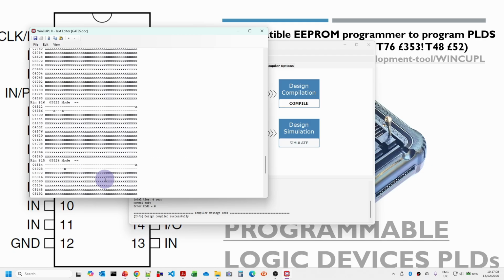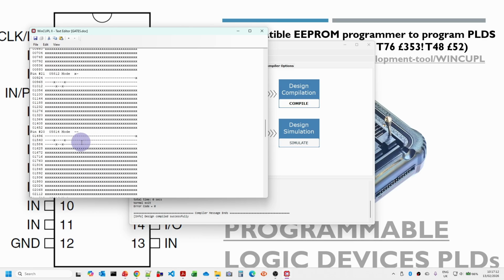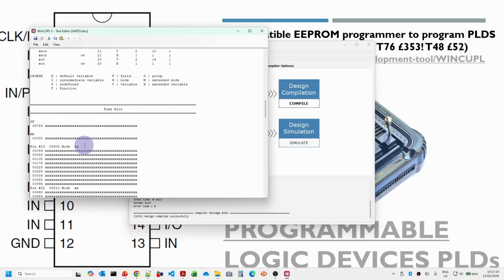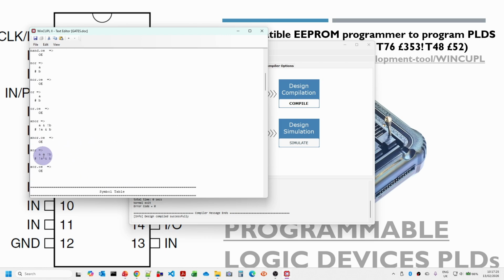This section here is the fuse map, and in the PLD series I explain exactly how you can work out what that means. You don't need to know about it in order to use them, but I think it's helpful sometimes in trying to diagnose certain problems. Then we've got the logic rules up here. So this is showing us that our exclusive OR is actually broken down into A and not B, or not A and B.